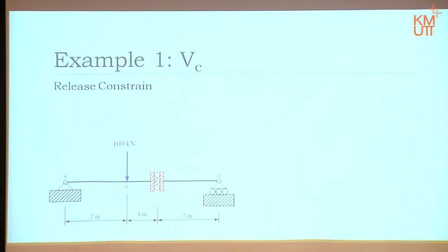Again, we start from 0 again, meaning we start off with the whole beam, the usual beam, right? With 1 point load. Then the first step is we release the constraint. Again, to release shear, that slide doesn't resist force in this direction, right? It resists axial force, it resists rotation, okay? But it doesn't resist sliding. Therefore, in this case, it does not resist shear. So we release it already. Then once we release it, the usual concept is we put them back in.